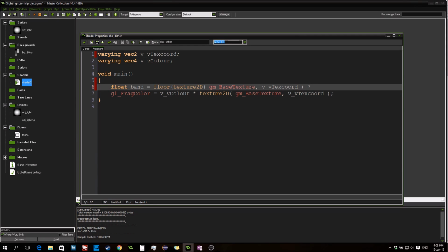We're going to be using 7 different images, so times 7. However, this here is a texture 2D, which cannot be multiplied by a float. We only want to get the value of that, and one easy way to do so is just to put .r, so we're just getting the red value of it.